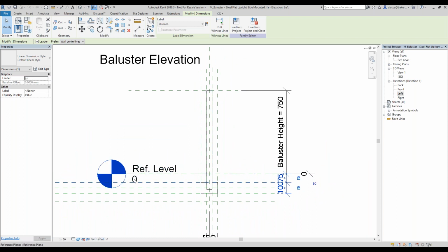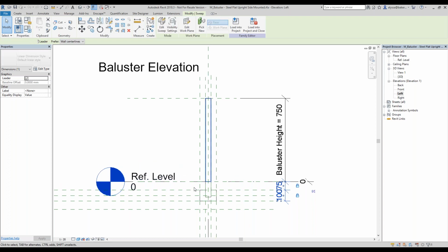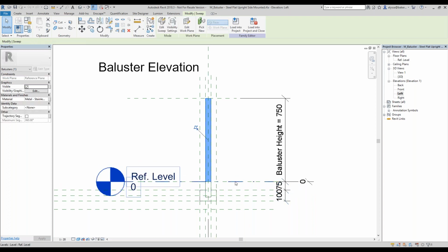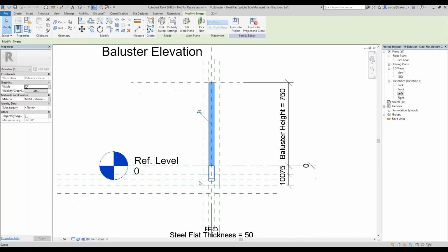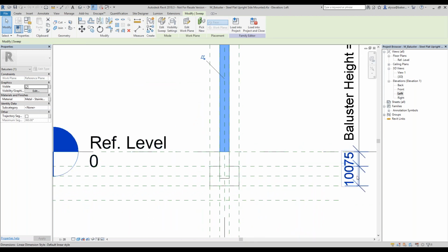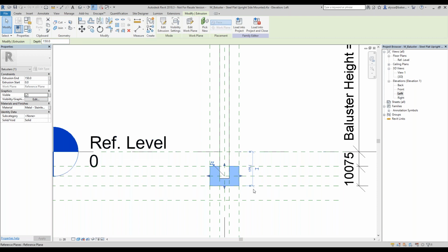Okay, with this in mind, let's see what I've done. The floor level is sitting there, right? And there's my baluster profile on the top, as the level of placement. And then down about 175 mils is the start of my side mounted profile. I've just added this on, so that sits below the level.